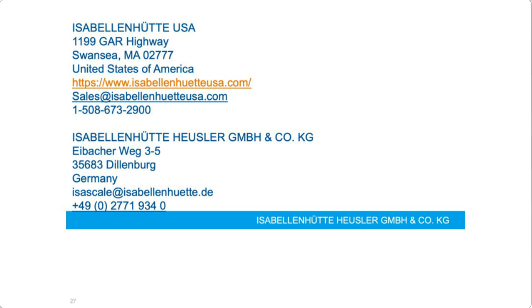We use Busmaster for that, which allows you, together with the CAN-DBC file of the IVT-S, to program the IVT to get all the functionality working: program cycle times, CAN IDs, overcurrent thresholds, or whatever you want to program in this product. There's also a guide on how to hook it up to your PC with Busmaster.